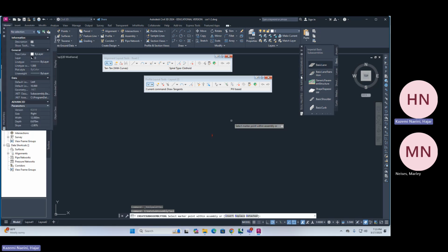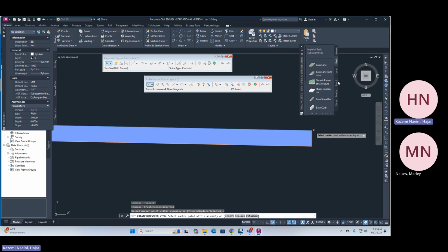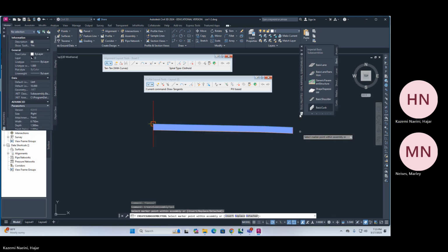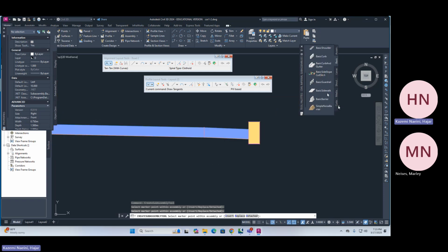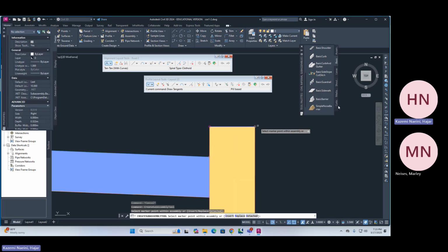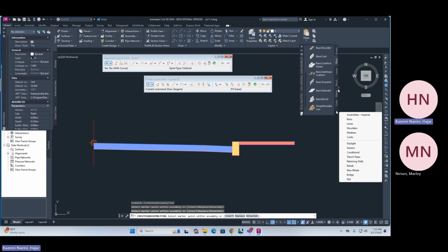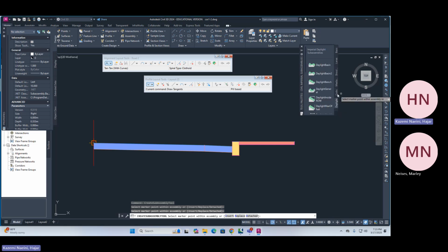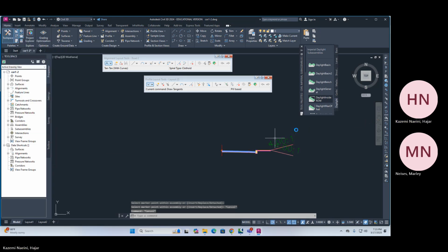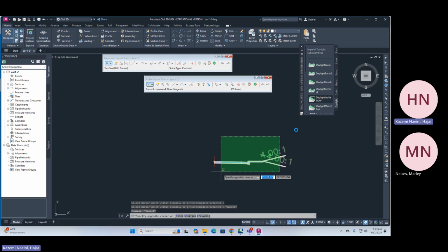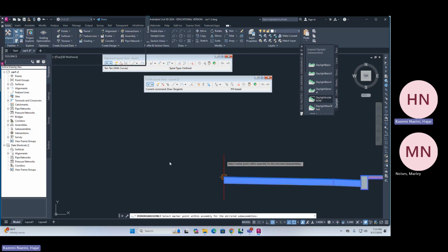Go to basic, add basic lane, add basic shoulder, add a basic curve, and we can add a basic sidewalk. And we can go to daylights and add a daylight inside row. And to make it complete, you can select that, go to mirror and hit the marker.